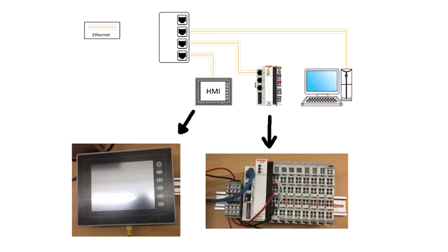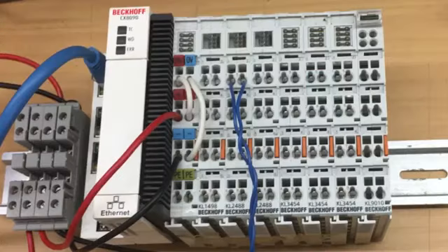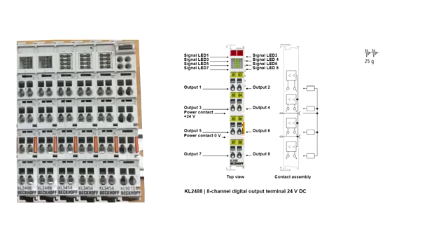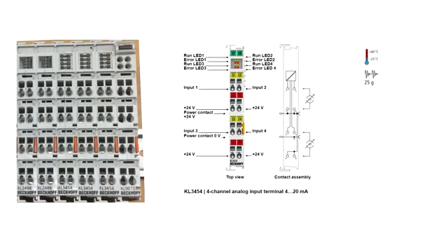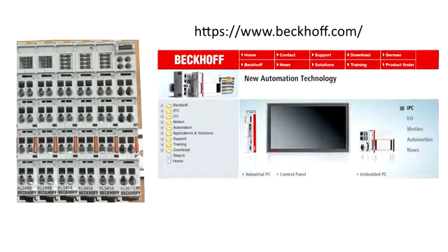Connect the Ethernet cables to the switch. Insert the wires to the appropriate module I/O. These are some of the modules. If you want to know more, go to the BECKHOFF website. Please be sure about the type of modules you are using.